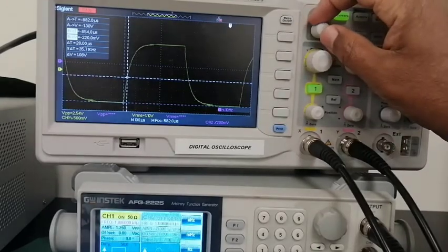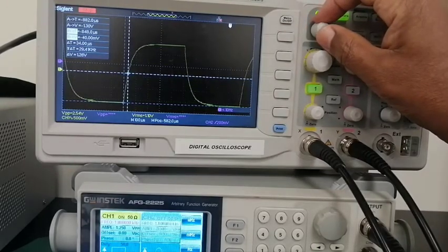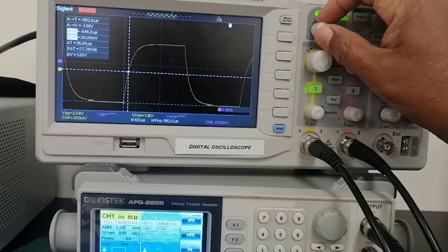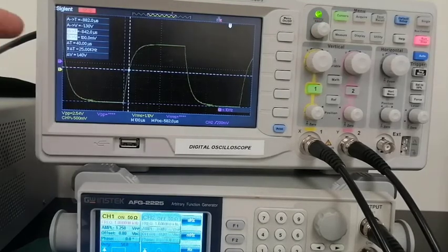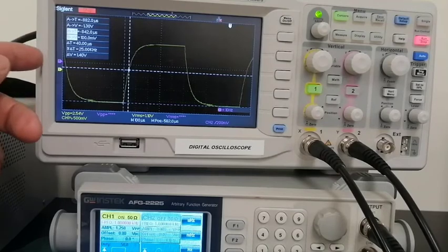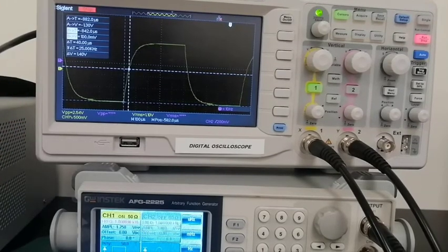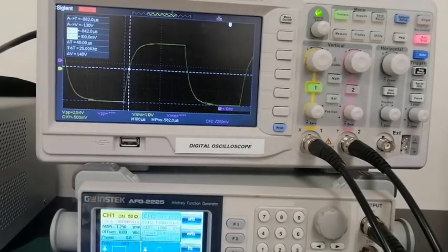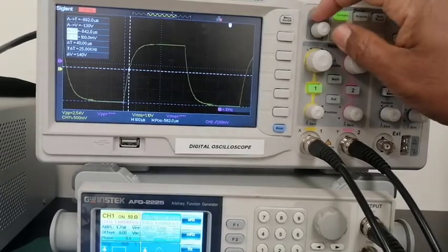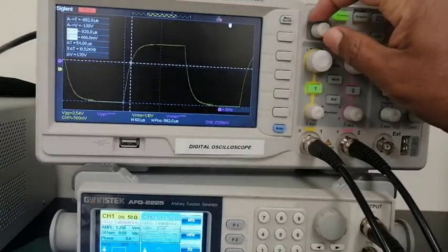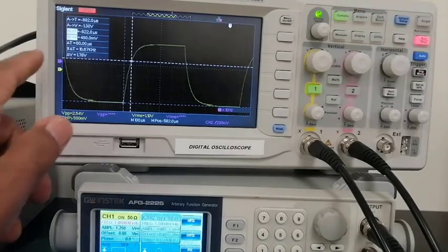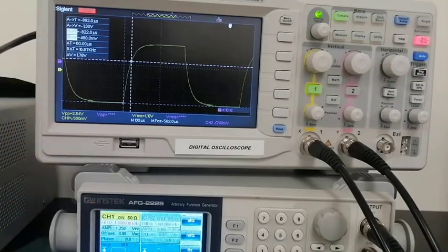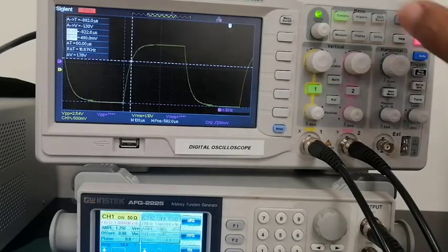The next measurement, delta of time 40 microseconds: VC shows 1.4 volt. The next measurement will be 60 microseconds: VC shows 1.78 volt.